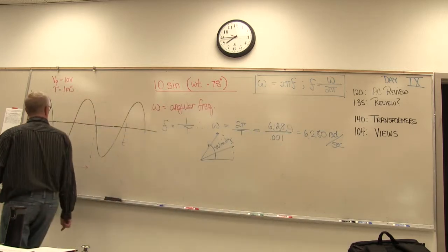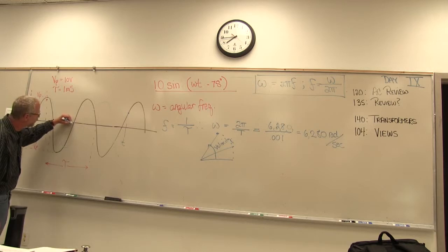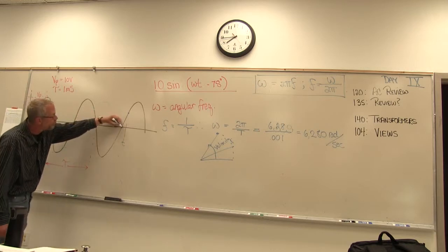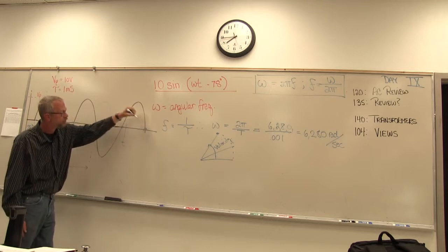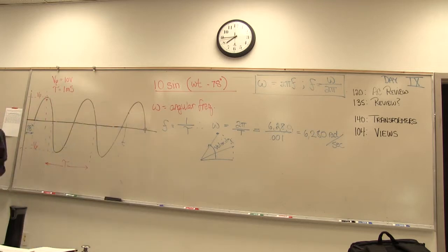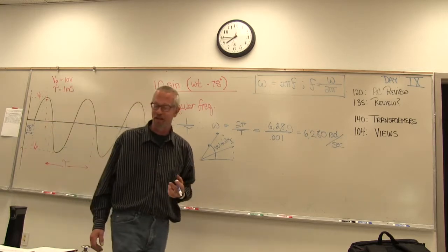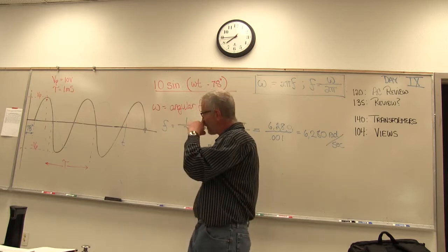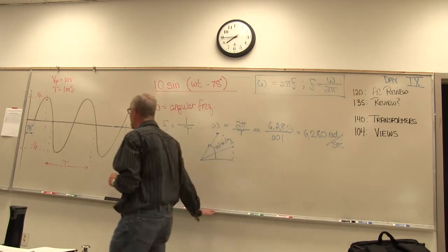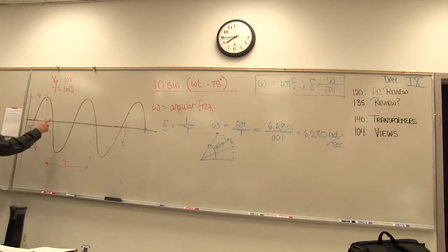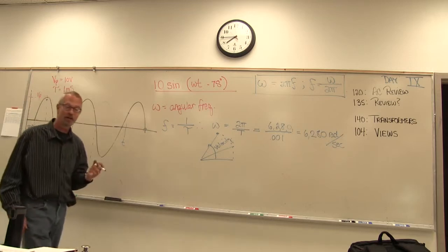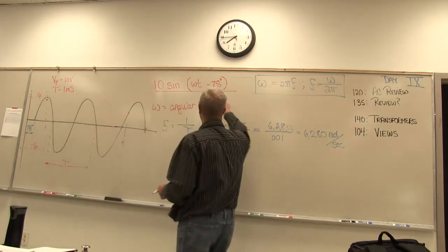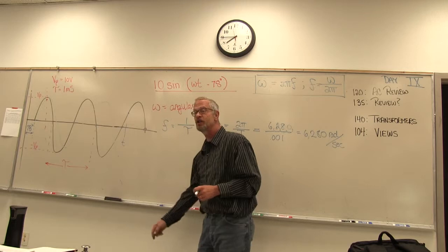Using this idea, we can also, if we wanted to, calculate when the output is equal to 0. Every 500 microseconds, every half a period, the output is equal to 0. But based on this 78-degree offset, we can't just say it happens at 500, it happens at whatever. And that 78-degree offset is a different amount of voltage change for any varying frequency. That's why we have to include that in our calculations.